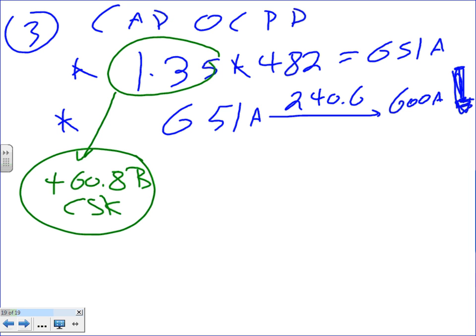Any question, guys, about the overcurrent protection device? So it's a 600 amp fuse. Is it wrong to put a 400 amp fuse? No. Max 600 amp fuse. If the manufacturers, guys, say put a 400 amp fuse, would you put the 600 amp fuse? No. If you don't know, this is how I want you, for the sake of argument, to calculate it.